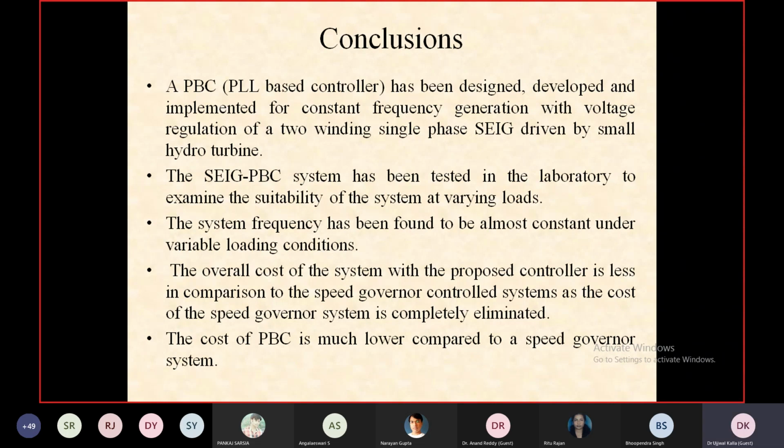If you have a 26 ampere generator, it may not generate more than 26 ampere under any condition. Even if you short circuit it, initially 26 ampere will flow, then the current will become 0 and the generator will become demagnetized. So it has inherent short circuit protection.